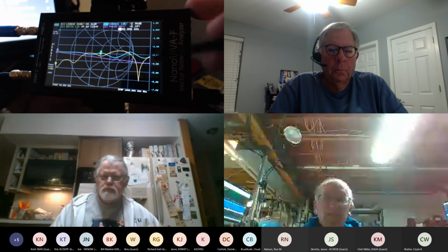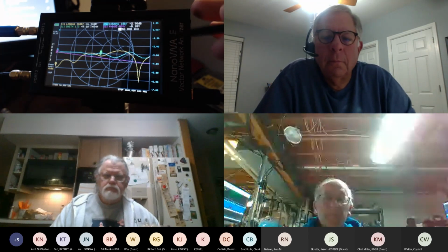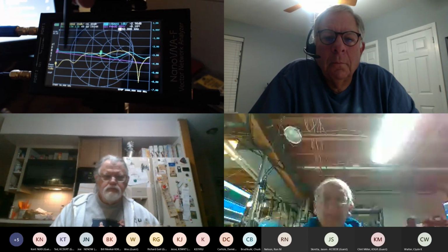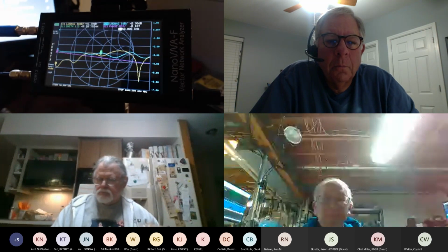And our scale here is 1 division per dB. So 0, 1, 2, 3. So we can see here this is a 3 dB attenuator, and we can see its characteristics. Again, 101 points from 50 kilohertz to 1 gig is pretty rough, but you can see the example here that's what we've got.